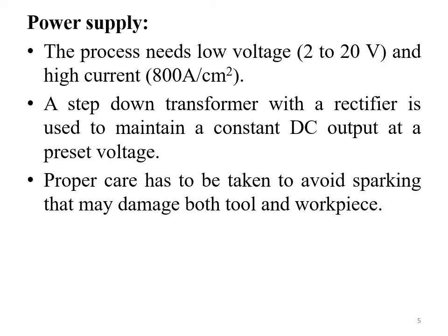While advancing the tool towards the workpiece, care has to be taken in such a way that at no instant is the tool making contact with the workpiece or coming within a very small distance, which may cause sparking or arcing, which may damage both the tool as well as the workpiece.